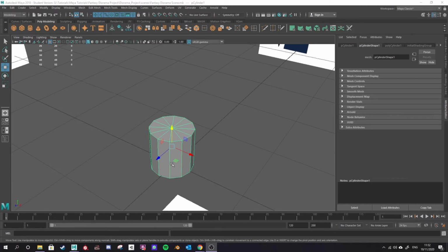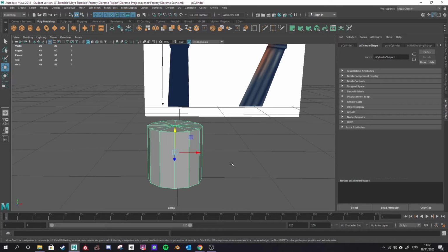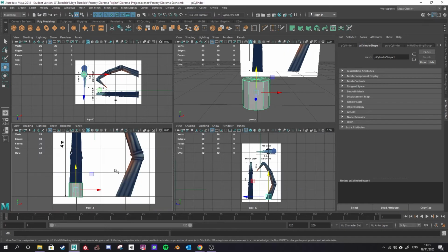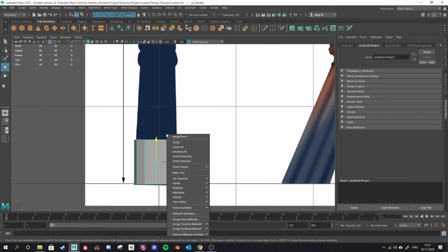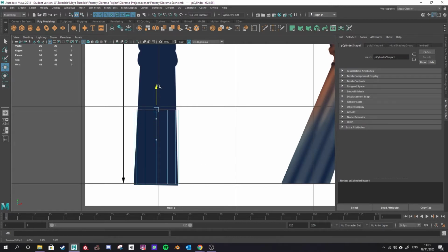So we're going to look at a few common tools now and 2 different workflows for creating the same objects. One of those would be using your Extrude tool. So I'm going to go into my side view here, and I'm going to use 4 to see through my model. It's 4 on my keyboard. Selecting faces, I'm going to select a rough marquee around the top and sides of this, then hold Shift and drag through to deselect the sides. So I've only got the top selected here.